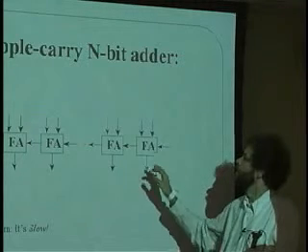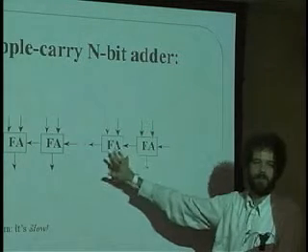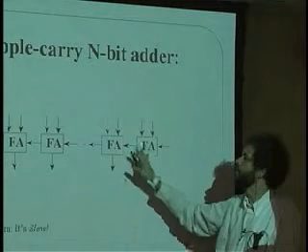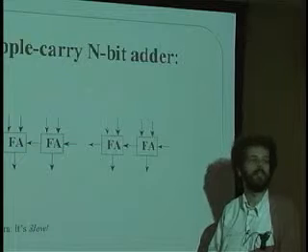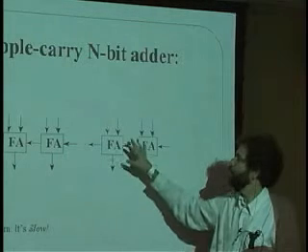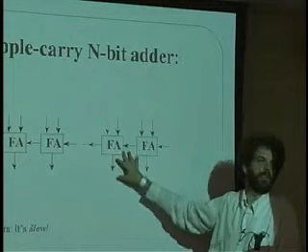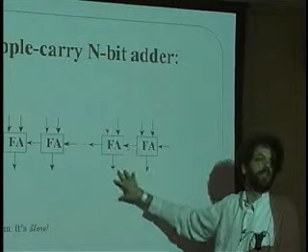So, in this simple case of just the ripple carry adder, in general, first of all, it has 2 issues. One is that it's highly dependent on what the numbers are that you're trying to add. If the carries only happen on the right-hand side, then the adder will be fast.